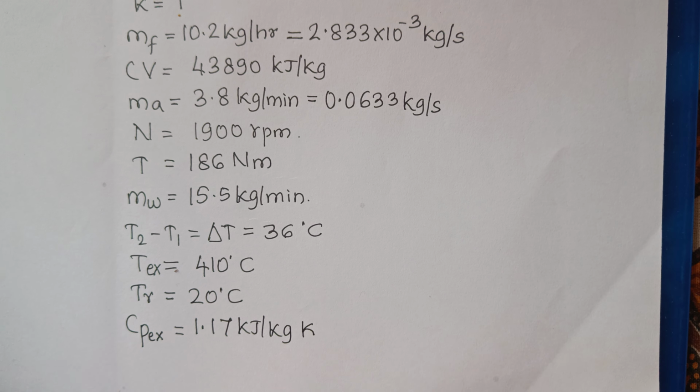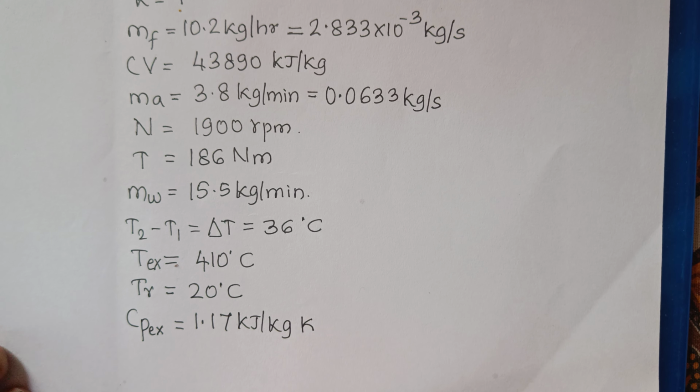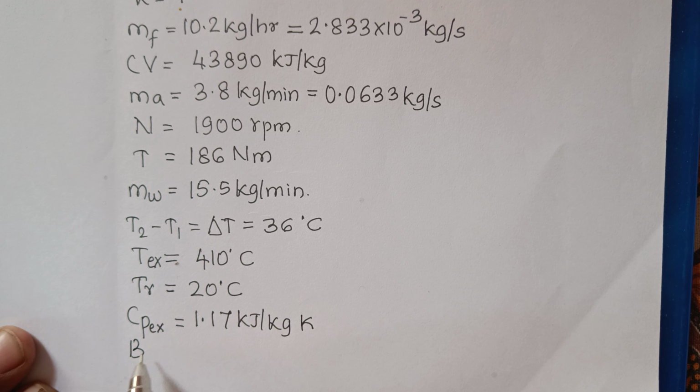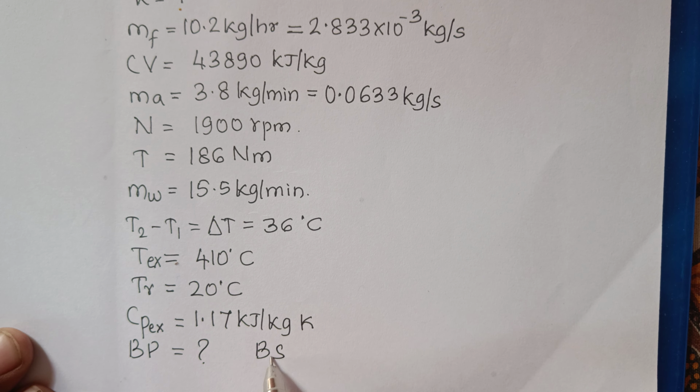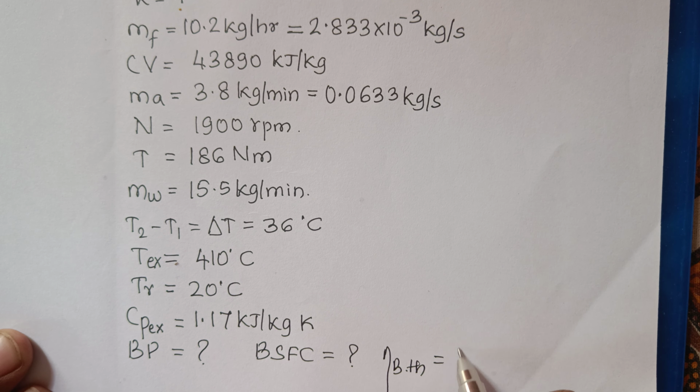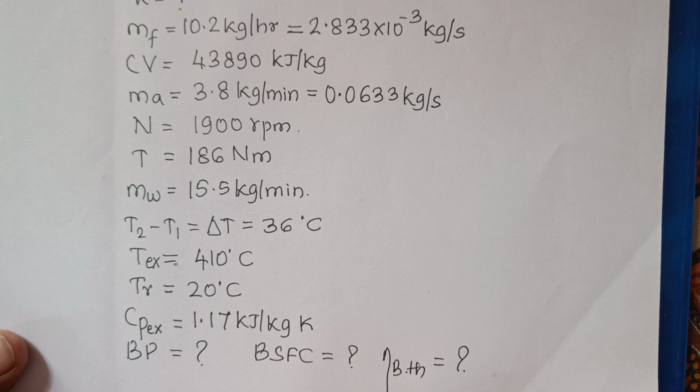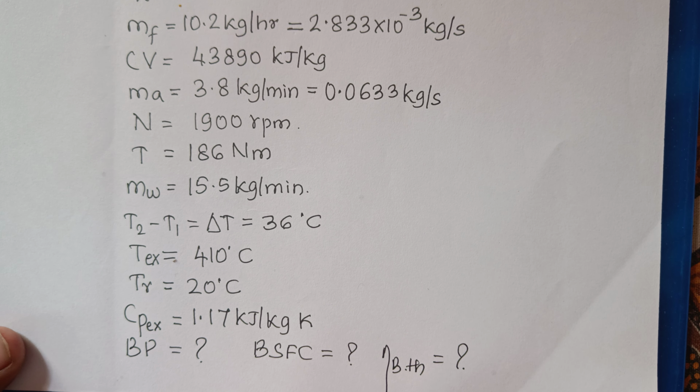Then what all you need to find out? First one is you need to find out the value of BP. Then BSFC. Then next is brake thermal efficiency, BTH, and then you need to draw the heat balance sheet.